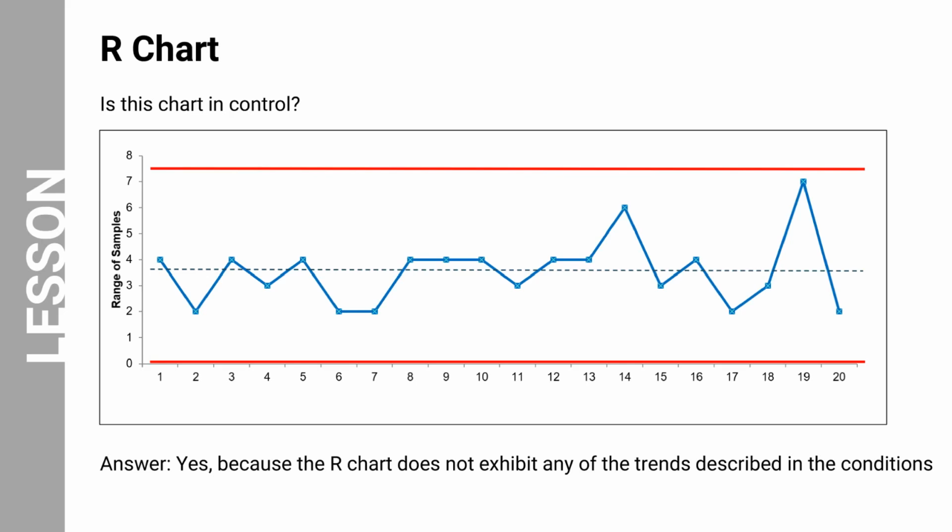In general, if you find that an R chart is out of control, then the X-bar chart is not valid. To aid in communication, it is best to circle any rule violations on the charts and then investigate the causes of the out-of-control situations. If you were the frontline technician who analyzed these charts, your next step would be to inform the quality control department about the data point that is outside of the control limits and assist in determining the root cause.